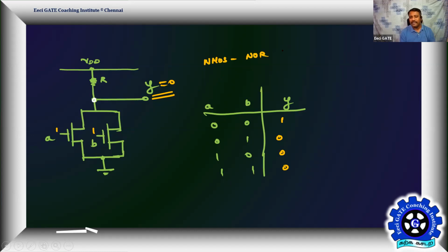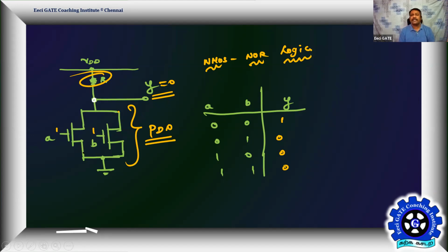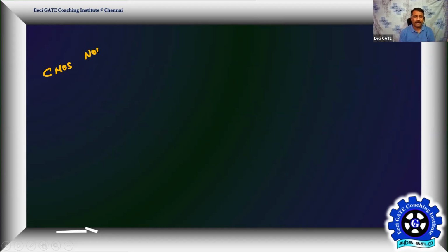So one can easily build an NMOS design. Once you comfortably make it, always begin with the NMOS design. Whatever logic function you want to make, build it by using NMOS. Then replace the pull-up resistor by using PMOS switches. How to replace that? You already have the well-built pull-down network. Just take the complement of the pull-down as your pull-up. Here the pull-down switches are connected in parallel, so you put the pull-up switches in series, and then automatically that's realized. So now you can go for a CMOS NOR logic. Easy everyone? Yes, CMOS may look a little complex, that's why you make it by using NMOS first. Then copy the NMOS pull-down design for the pull-up, but complement it. If they are parallel, make it series. If they are series, make it parallel. So that's a CMOS NOR logic.